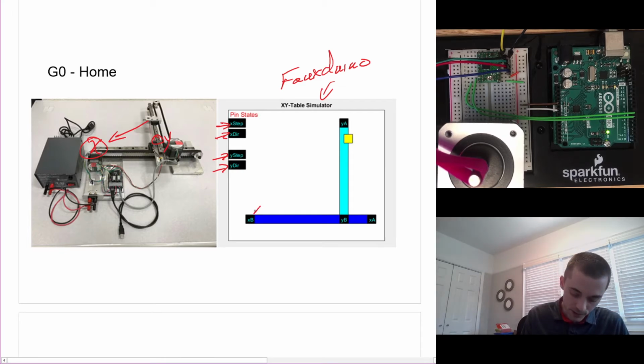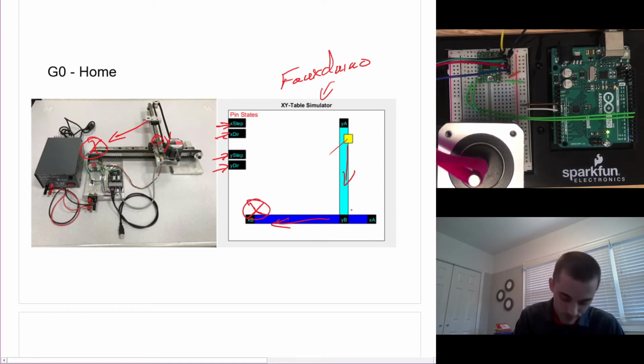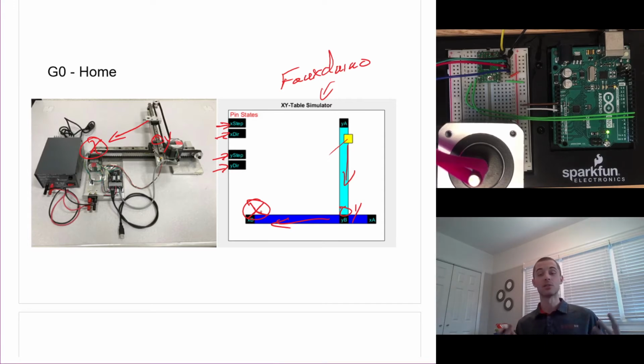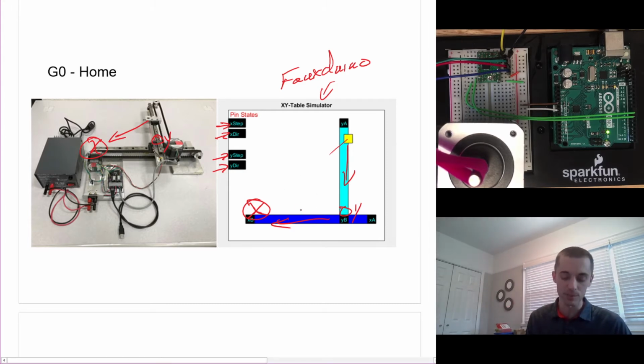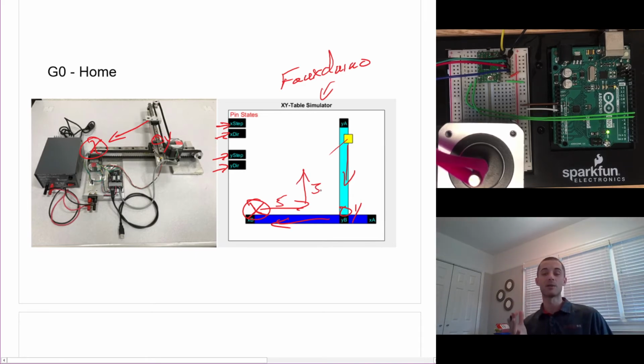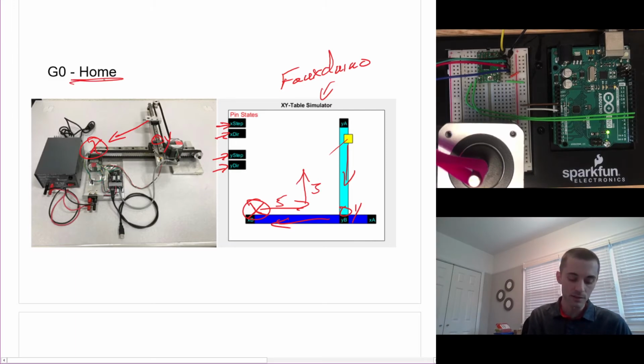And so the home position is actually down here, where we'd be able to get this carriage both to go down this way and this way, and hit switches right here for the Y and right here for the X. I don't know why I'm drawing them again in that strange way. But that's the goal, is trying to get it to a specific location. So then from there, you can reference moving to, let's say, an X position of 5 inches and 3 inches in the Y, right? You know exactly where to move because you have found your 0, 0. You have found your home position.